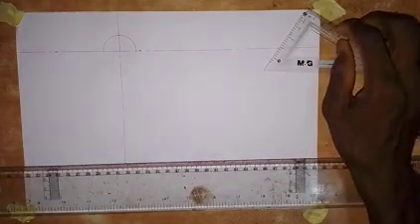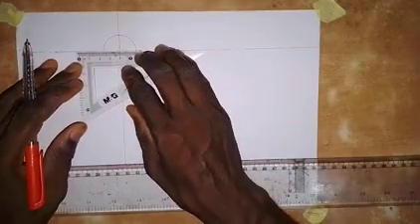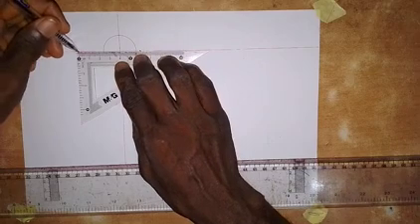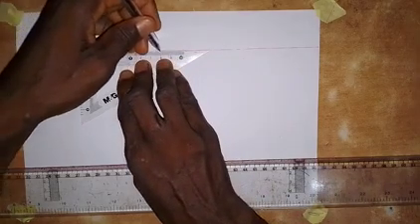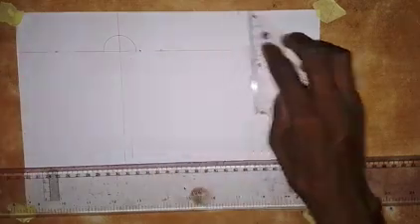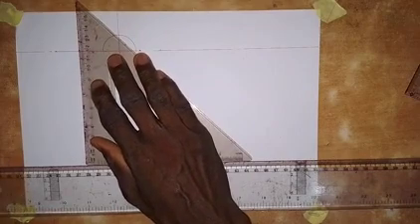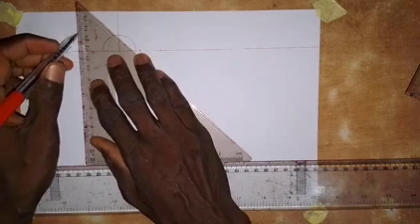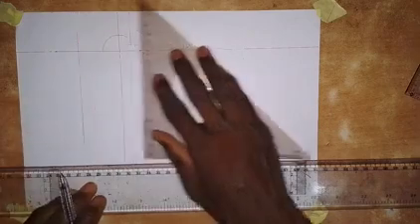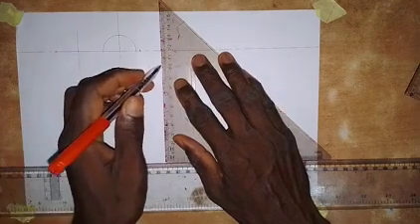Okay, so the next thing that I'm going to do is take a measurement of 40 millimeters from this point, 40 millimeters from here to this side, from the center of the circle to this side. Then I will also take 40 millimeters from this center to this side, making 80 millimeters. Then I'm going to draw a vertical line from each of these points. So I will draw a vertical center line here like this, and then I will also come here and draw a vertical center line down here.